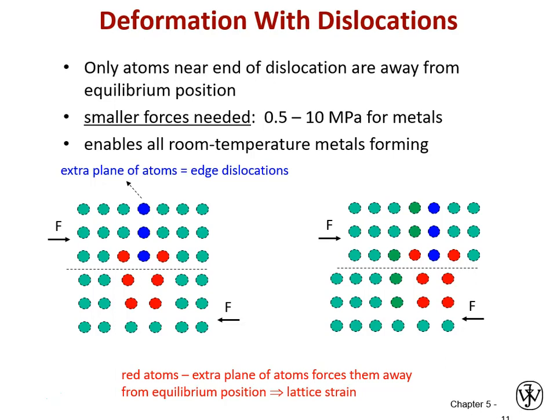And again, it's coming from a double hit. We had to move fewer atoms out of their equilibrium positions, and because the dislocation preloaded those atoms that we did have to move with a bit of energy to begin with, the amount of energy necessary to move them through their most non-equilibrium point was less. This is most importantly for us who need ductility in materials. This is significantly less than the energy necessary to form a surface for fracture.